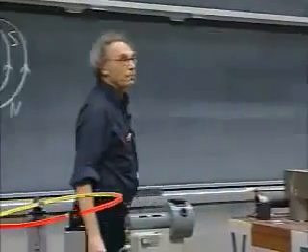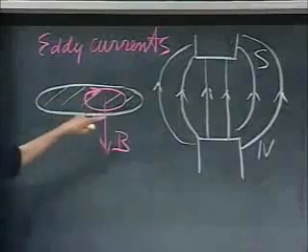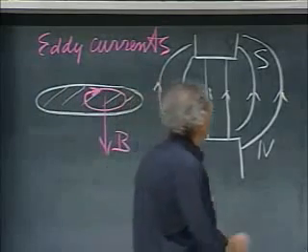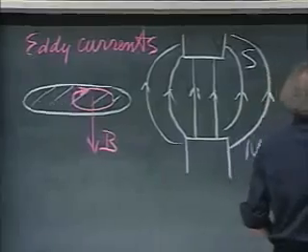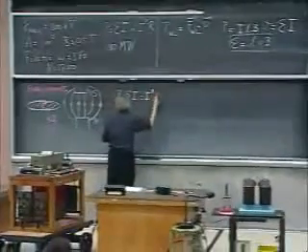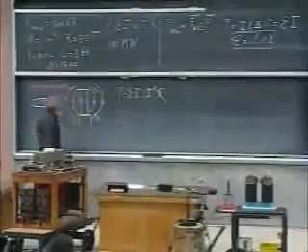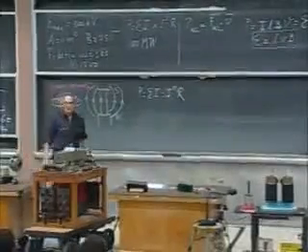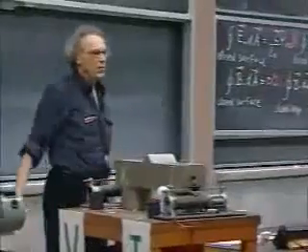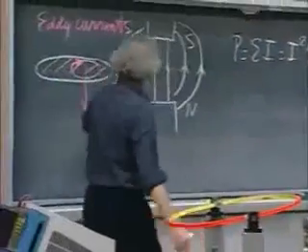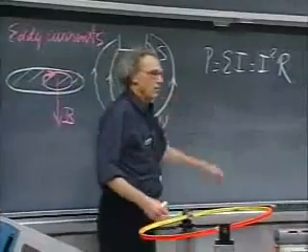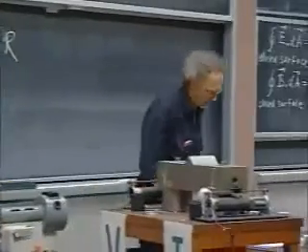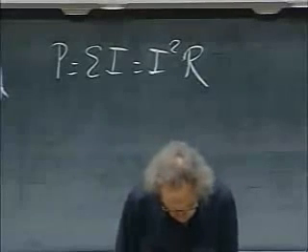The eddy current produces heat in here. The heat is the product, joules per second, of the power, E times I. I squared R always comes down to the same. So this disk will heat up a little bit. The resistance now is the resistance there. And that means that the disk will slow down. At the expense of kinetic energy, heat is produced. And it won't go as fast through this field than the situation would be if there were no field. And we call that magnetic braking.